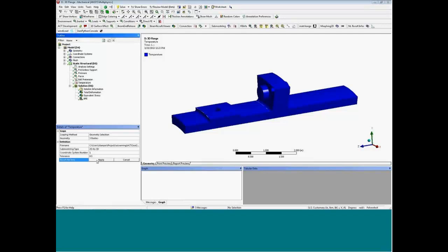And then there's also some tabular information here. So there's 2 load steps in this structural problem. What temperature results we want to map in from the thermal result file? So you can see you can pop up little tables, different things like that, little drop downs. You know, there's a lot of things you can do with the extension.